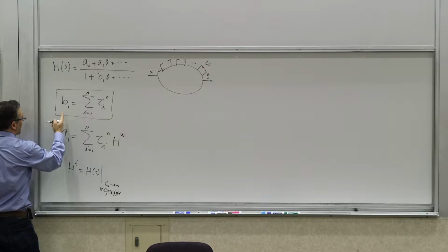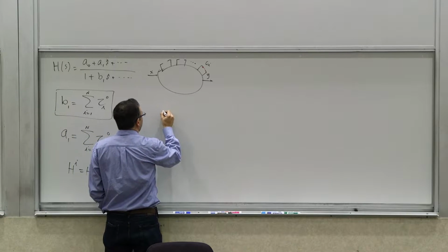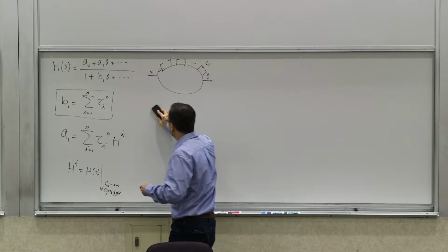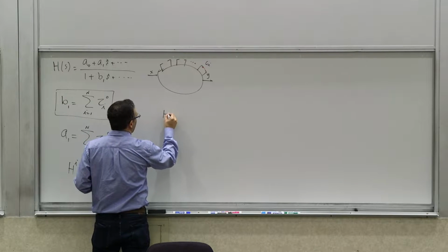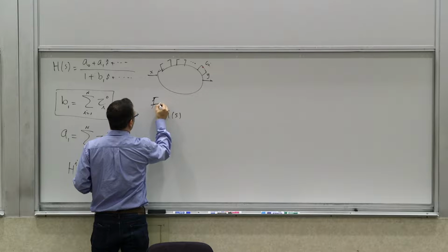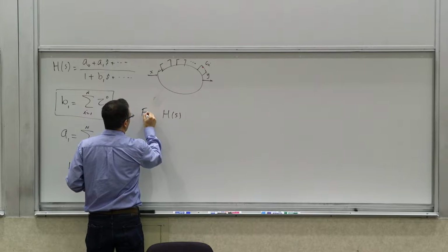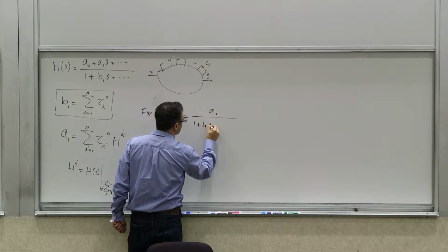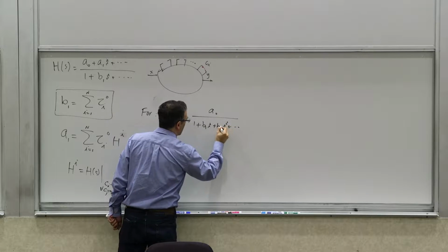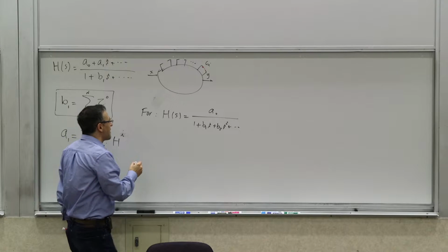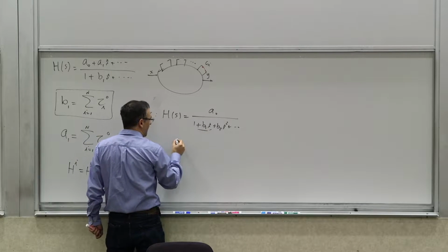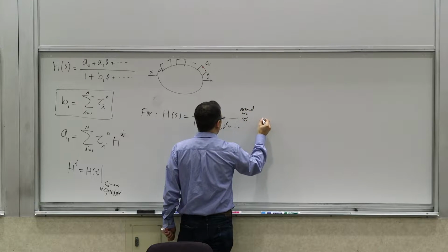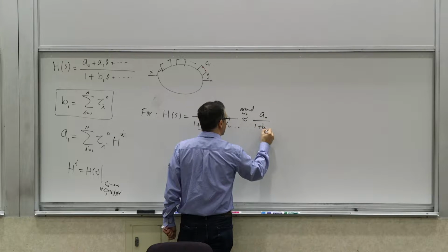So the other thing that we did last time was that we said, assuming that you have no dominant zeros, meaning that H(s) has this form, so there are no dominant zeros, you can approximate the system around omega h to be a first order system, and this is an approximation.